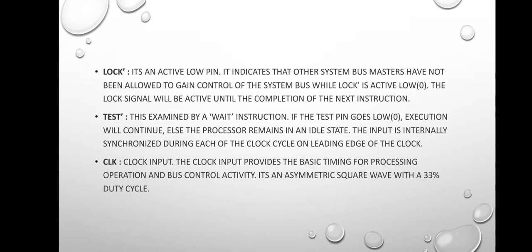And TEST bar. This is examined by a WAIT instruction. If the TEST pin goes low, execution will continue, else the processor remains in an idle state. The input is internally synchronized during each clock cycle on the leading edge of the clock.